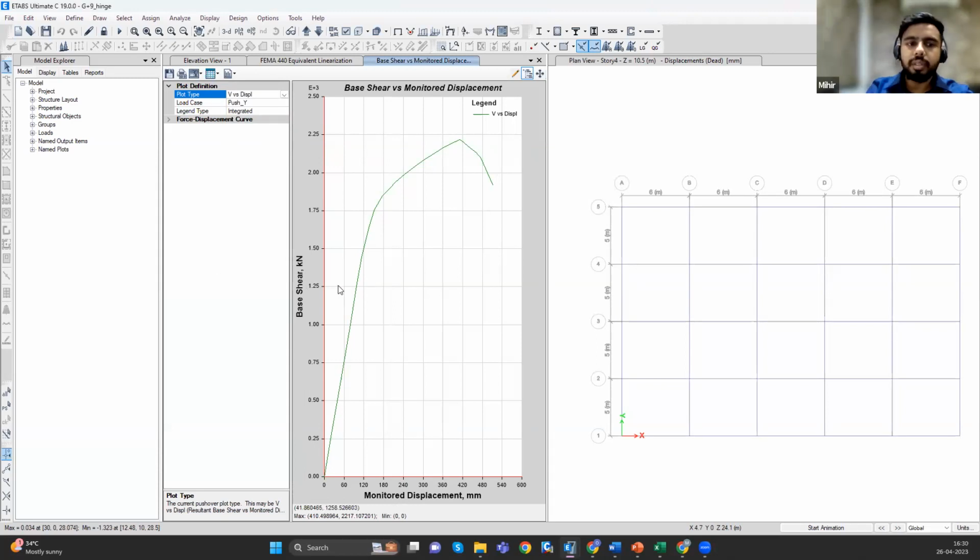As of now, we have done it for the pushover in y direction. It will be similar for the x direction as well. Another important thing that I want to highlight: when we apply the pushover, and suppose you are using the mode option, so the first mode, in case that is the y, then you will choose the pushover in y direction and give that as mode 1. But that is just the name. You can apply it in the push y and push x, it will be similar, but for the result interpretation part, it will be easier for you to understand. The mode will be defined for x as mode in first direction in the x way. So we will be using push x and defining it for the mode x and choosing it as 1.